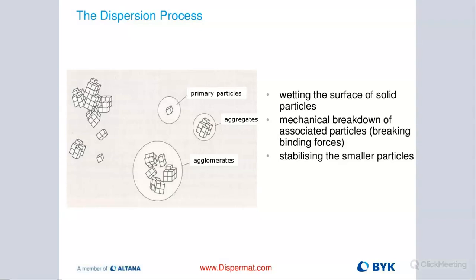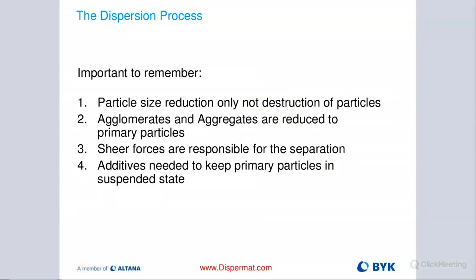So it's really important to understand that the dispersion process is actually always two parts. It's the pre-dispersion with the blade, and then the fine grinding or the milling when we use the media. Or some people, if you don't want to use media, you could use something like a rotor stator for very low viscous materials that will also allow us to get to super small particles.